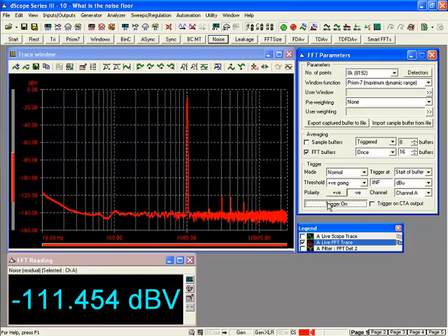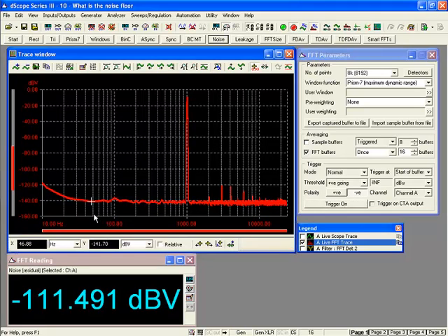Turn the trigger on, and again we can see there is the noise at the lower end of this FFT here that intersects the y-axis at approximately minus 140 dBV, but that is telling us that there is, if you look at the reading here, approximately minus 140 dBV of energy at each and every one of these data points, these bins in our FFT.